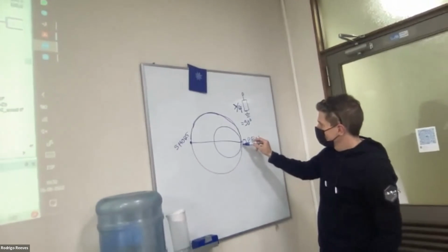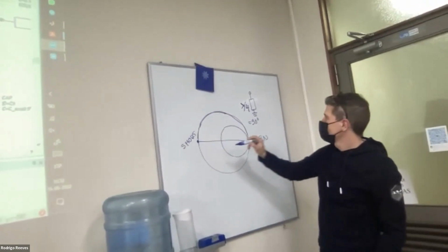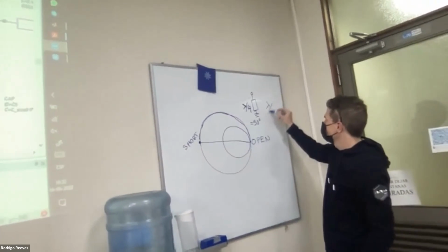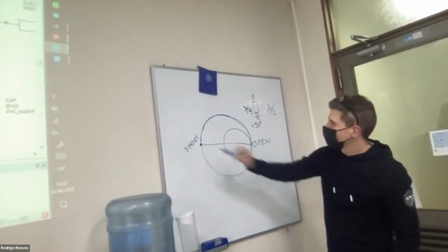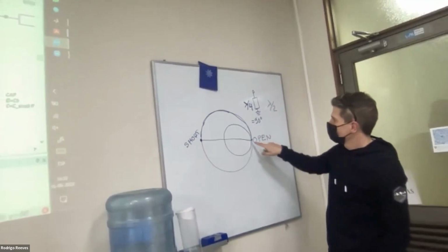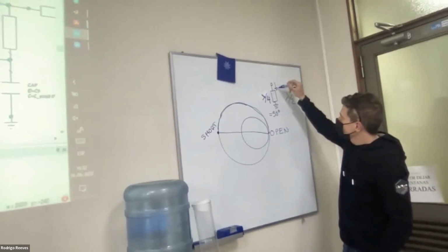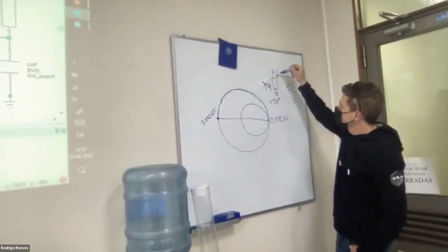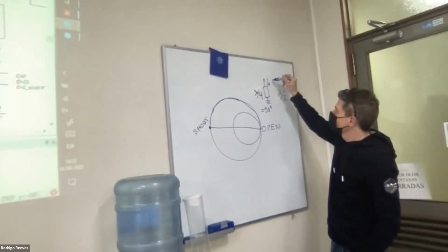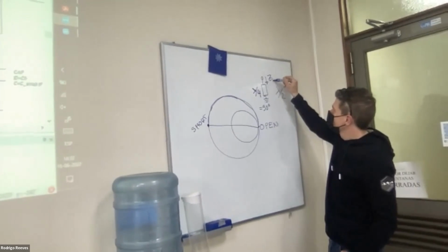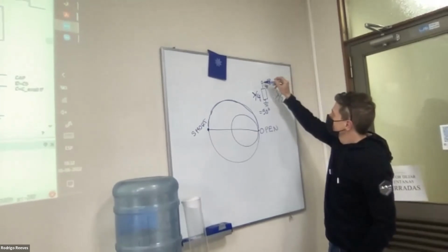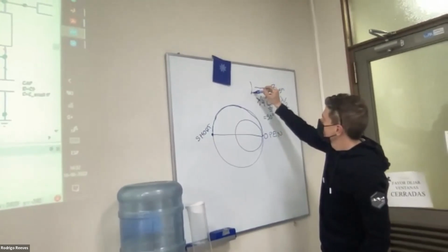And then another one would be that you are back there. So that would be half wavelength. You would go back to the short. So now this is ideally an open, looking in that direction. So that impedance is now very high. Z super high.